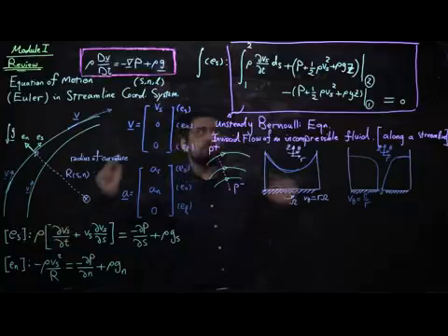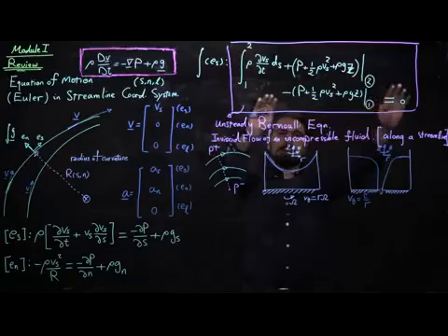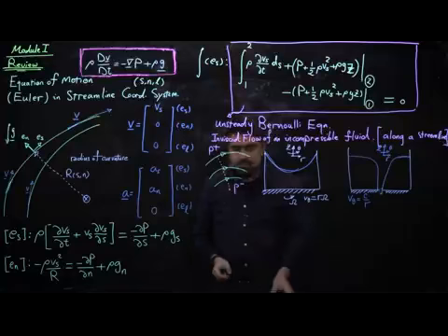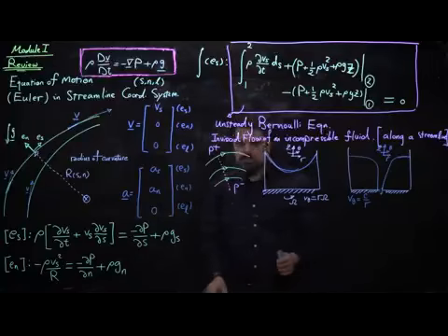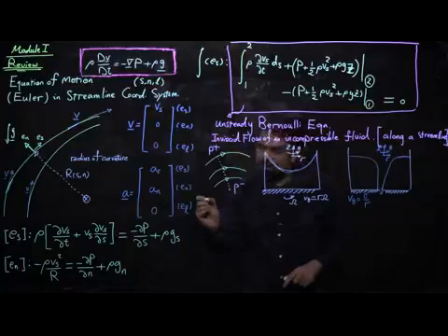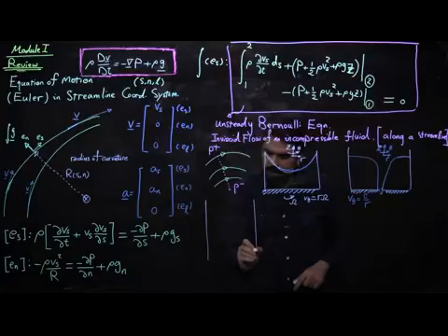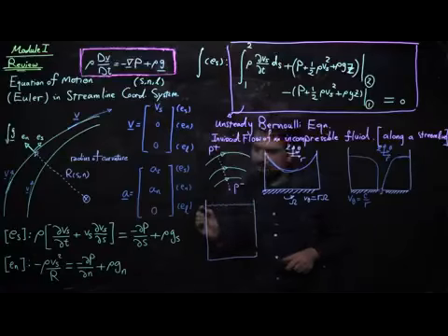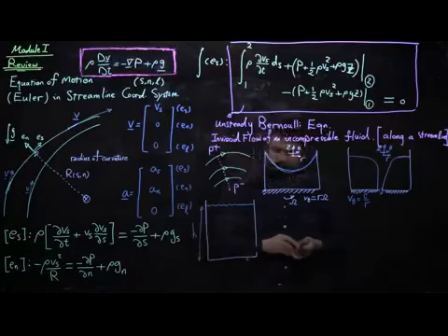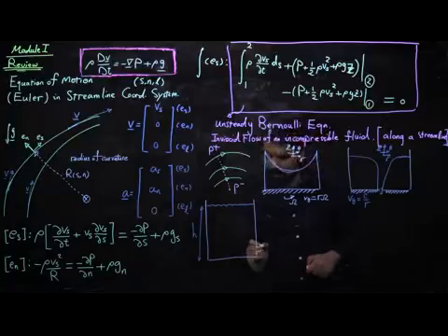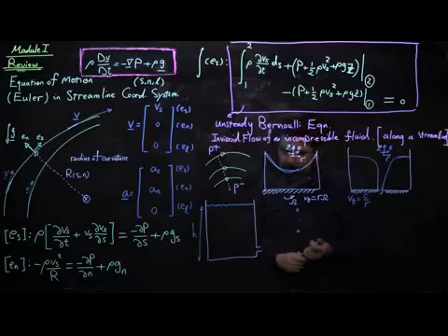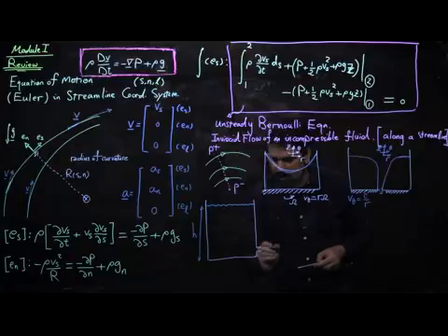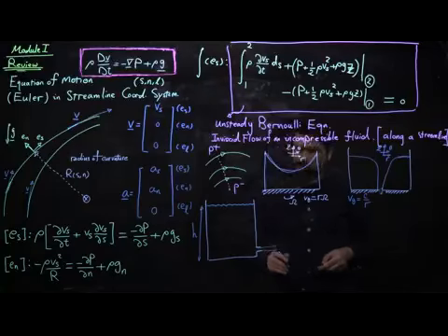Euler equation parallel to streamlines, again, remind ourselves, gave us Bernoulli equation. And Bernoulli equation was something that we extensively used in certain interesting problems. One interesting problem that we studied was the case of a tank that has a certain liquid inside with a certain large height h. And we ask ourselves what will happen if we open a small orifice at the very bottom of the tank. And you can imagine that the large hydrostatic pressure will force the liquid jet to come out.